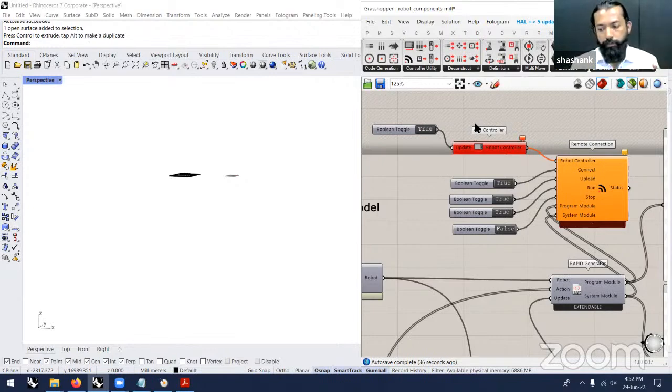All of these plugins that try to connect to ABB Live will offer to install ABB runtime components. If there is a multiple dependency of ABB runtime components, that might create an issue. And if you install the ABB runtime component in separate folders for robot components and for robots, that might also create an issue. So try to install it only one time. If you've installed RobotStudio, that is enough. It installs the ABB runtime component by default. You will not have to reinstall that again.